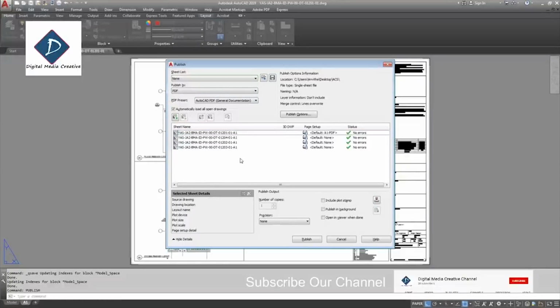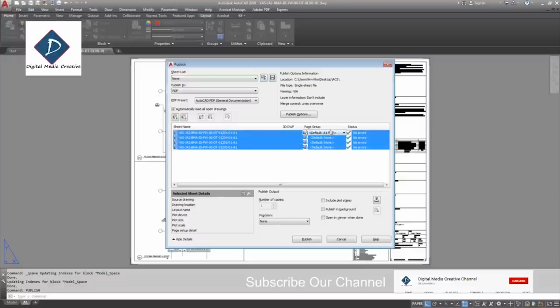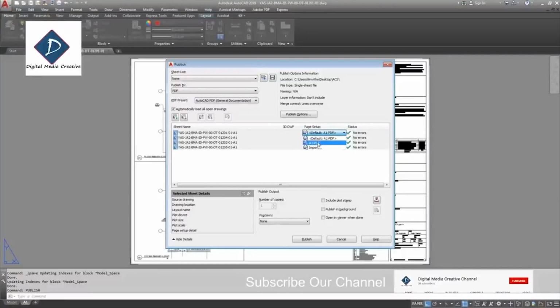So which way can we do it? It's easy, just select all, then select the settings, so you can see all the PDF done. So the next thing, make sure to choose what you want to publish to. If it's printing, you can use plotter and name setting, and if it's DWF or DWFx, you can select this one, and PDF. And we are going to print as a PDF, so we are just clicking PDF.